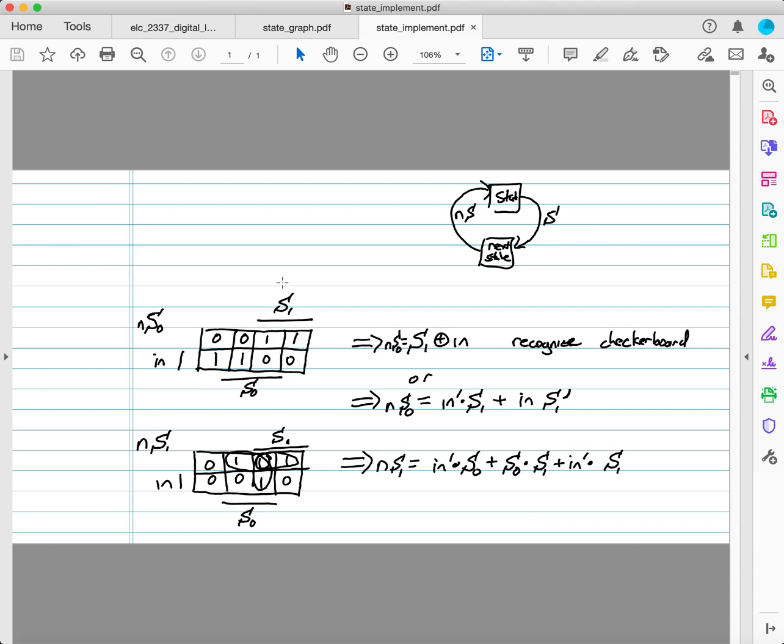So just walking through the Karnaugh map, you can see I've got my state bit set, most significant, then the least significant state bit. I'm using capital S for my state, and just to make it easier to see and tell what my state bits are, I put these little serifs on the end of them. You don't have to do it. It just, to me, when I look at it, I go, oh, that's a state bit. Just makes my life easy. I just number the subscripts in the order of them. So that's the left, state bit 1, state bit 0, the right, the least significant. And then my inputs, like I said, are on the vertical part, handling which number of the rows. So you can just see it's set up.